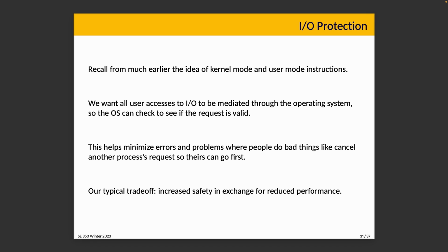And for some hardware devices, we're not that worried, but for others, if we send rogue commands to an air conditioning system, we might end up doing what is called short cycling it, which is it runs for a very short period of time before switching off again. That turns out to be bad for your air conditioner. So you want to install some safeguards that prevent those kinds of bad behaviors from happening, even if they are unintentional.